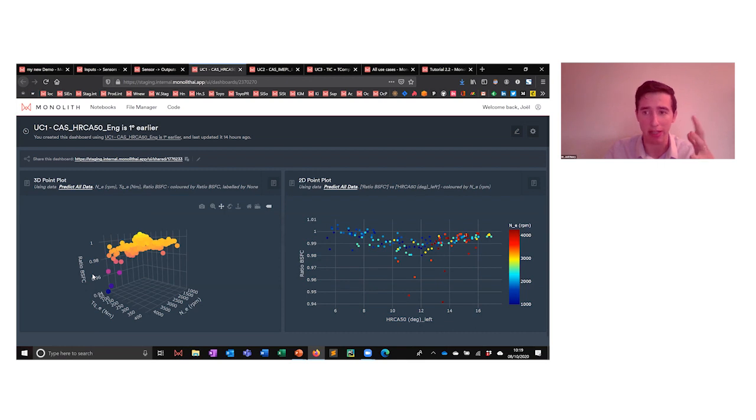That's an indicator of how much fuel you consume, and it's the ratio between my original data and my new data with the combustion slightly earlier. A value of 1 means that an earlier combustion has no effect on the fuel consumption. A value above 1 means higher fuel consumption, and below 1 means lower fuel consumption.